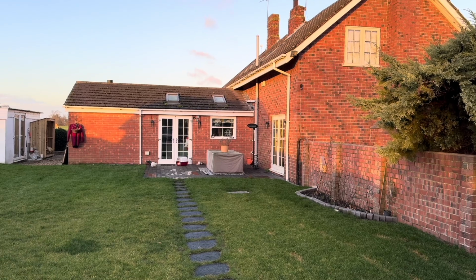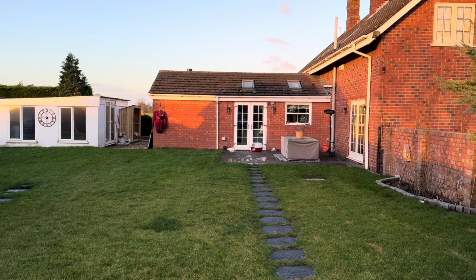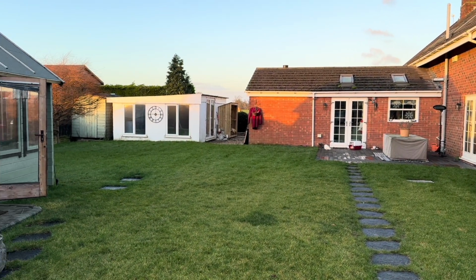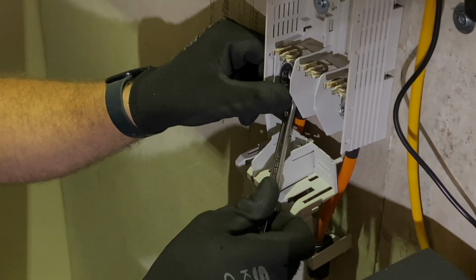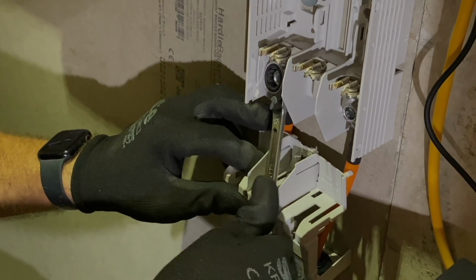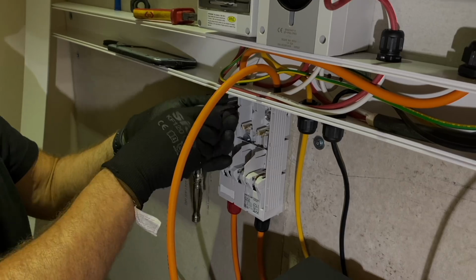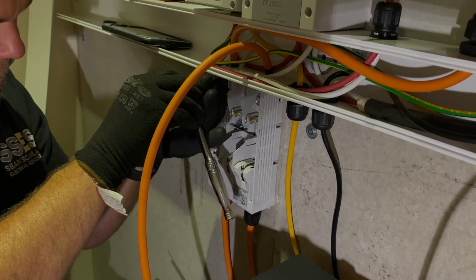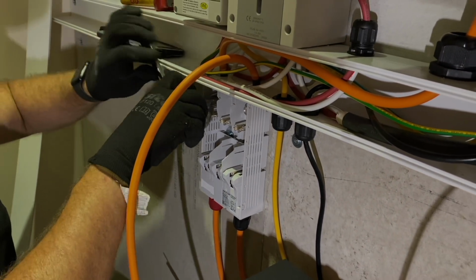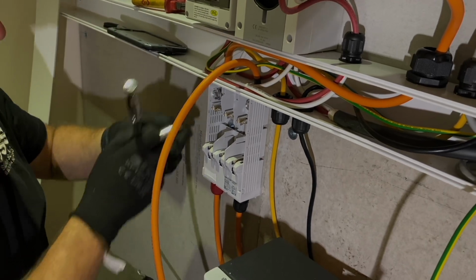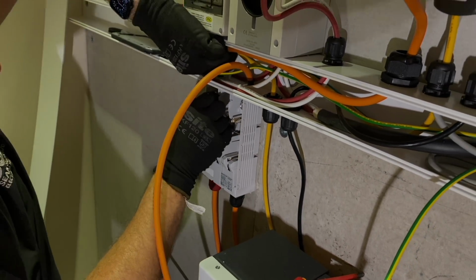We need to consider volt drop on the DC side as well. If batteries are located a distance away from the inverter, then we won't get the efficiency of the DC conversion to AC from the inverter as the voltage will have dropped, which will impact the AC output. This is why guidance says that batteries need to be located as close as possible to the inverter and why manufacturers supply pre-made battery leads to plug them in. This is because the manufacturer is ensuring that the batteries and inverter are working at their optimum level.